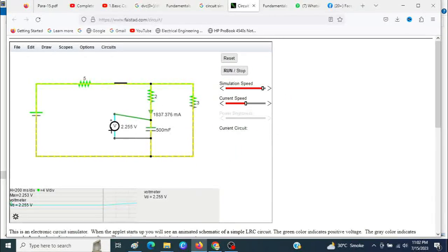You can see the voltage is gradually increasing. From the graph also you can see from zero level it is gradually increasing, 5.5 now, 6. Keep monitoring this, and when it goes to 9.375, the charging current should stop and this should level up.